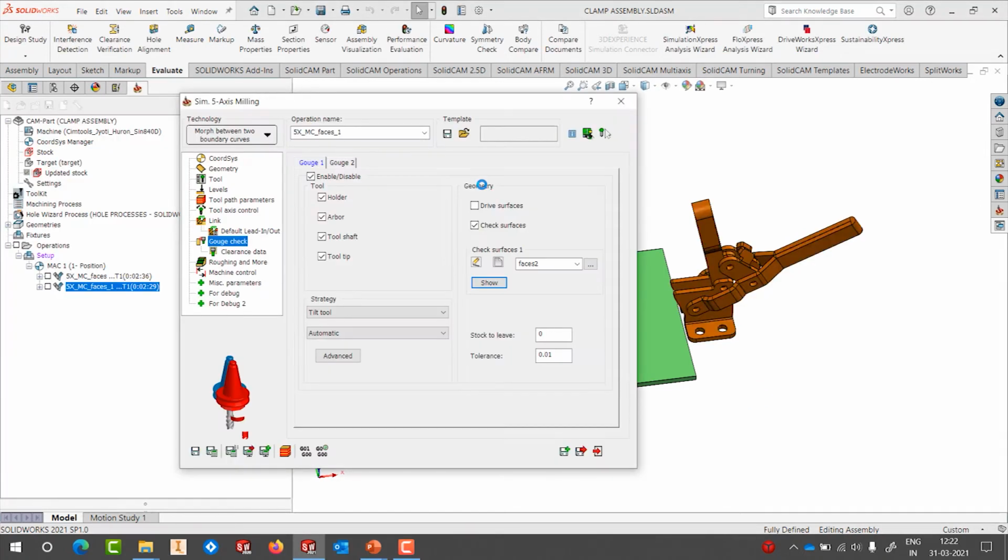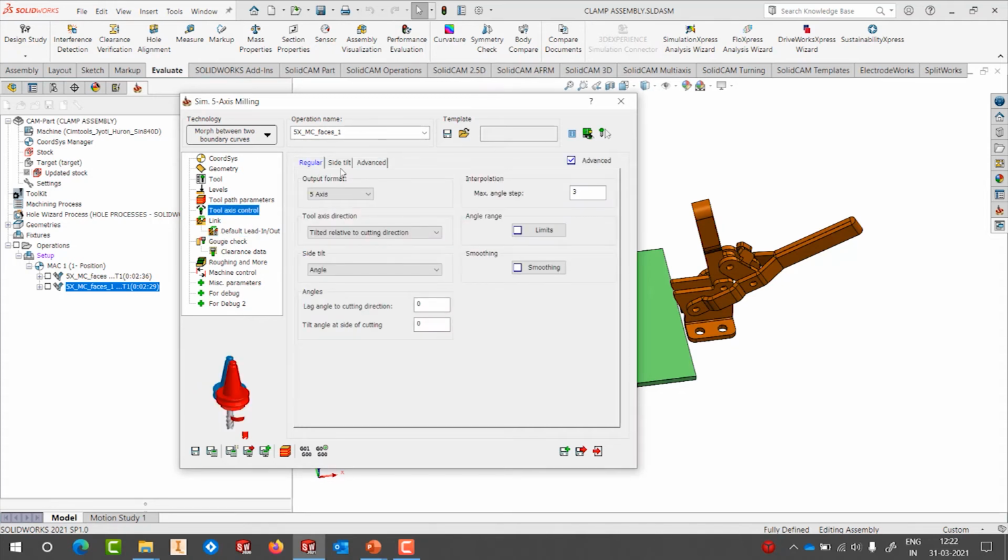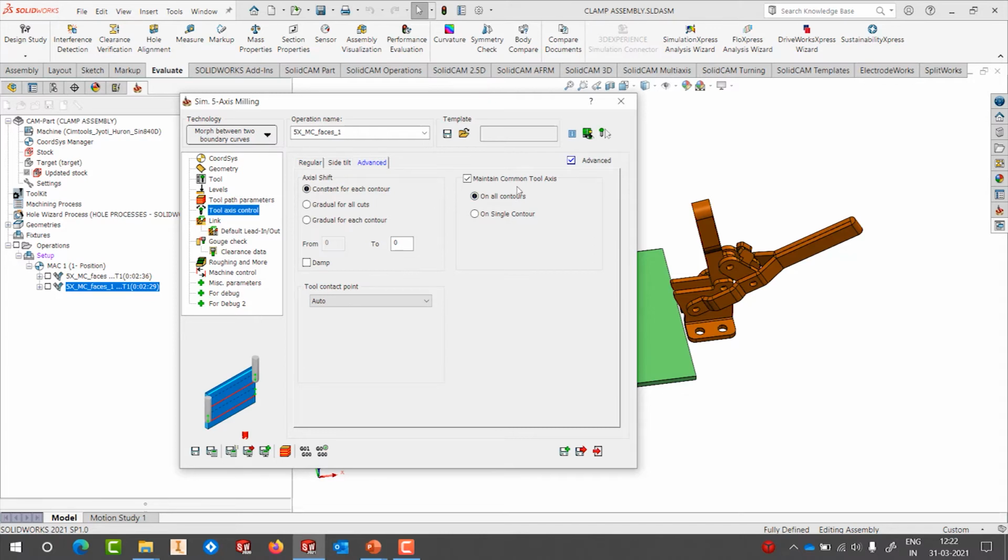But although I have said tilt tool, I'm not going to be using this tilt tool. What I'm going to do is use what we call a common direction, or SolidCAM will find the best possible direction for machining this particular surface by avoiding the collision geometry that was defined. So it's probably going to be something like a 3+2 toolpath. And exactly this is how it looks.